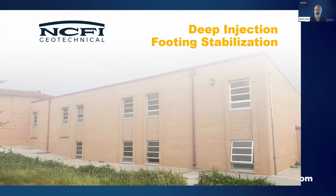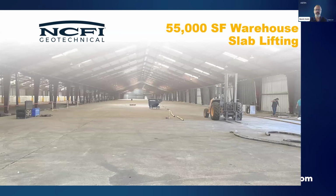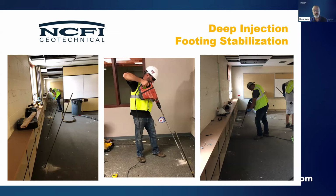We can also stabilize footings, lift footings as well. This is a project that we did up in the Wyoming area. We had to drive deep injection tubes at an angle to get directly below the wall of this two-story building. Once we determined that angle and started injecting, we were able to stabilize the slab. And by stabilize, I mean we were able to lift just a slight amount, just to know that we had filled all the voids and had stabilized underneath that, not the slab, but the footing. It was a narrow spread footing. I think it was 18 inches wide, if I recall.